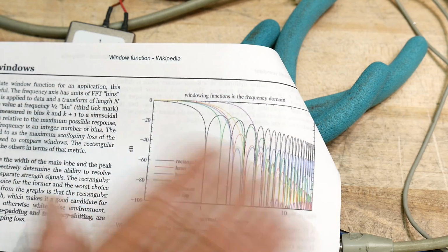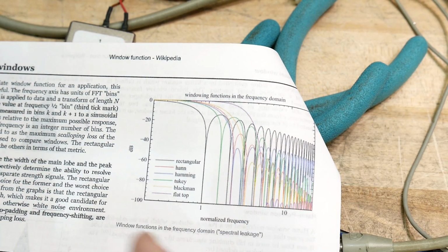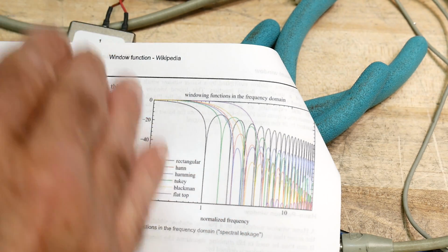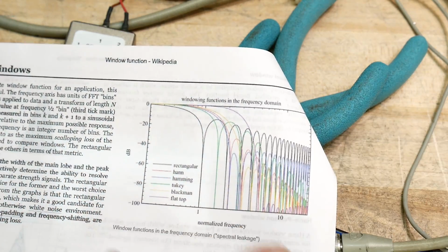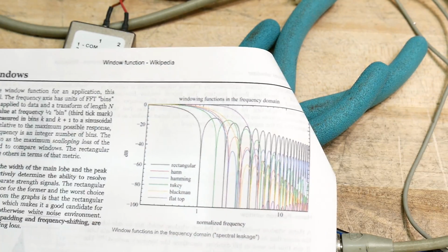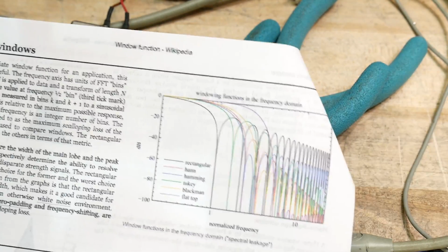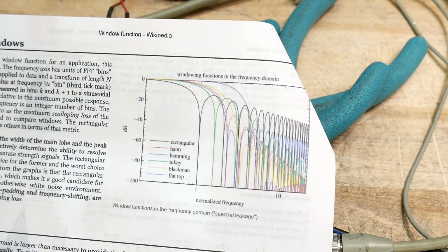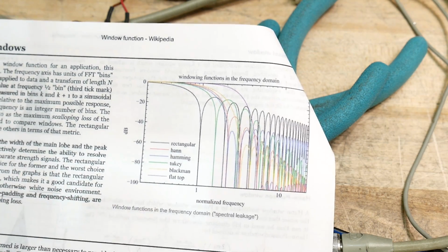And you do that with these functions. So you can imagine it's some type of averaging. So if you have data that's kind of going down, you want your averaging filter to also go down. You don't want it to just go down and then stay flat. You want it to continue. So these normalization functions, these window functions, allow you to use a limited number of data in an application where you need an infinite number of data.